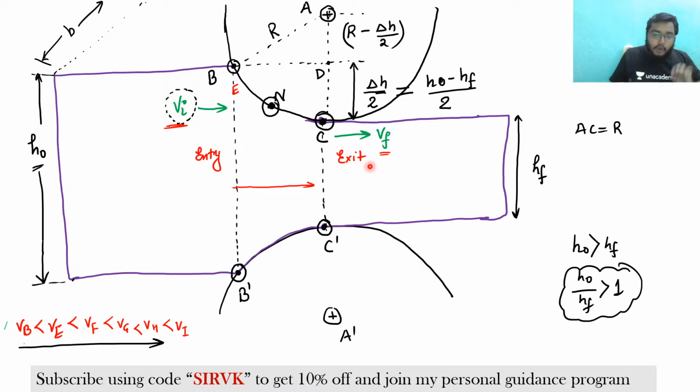So we can say that VF is going to be greater than Vn. Due to this final velocity VF, the workpiece will be slipped out. So VF minus Vn by Vn is going to give me the forward slip.